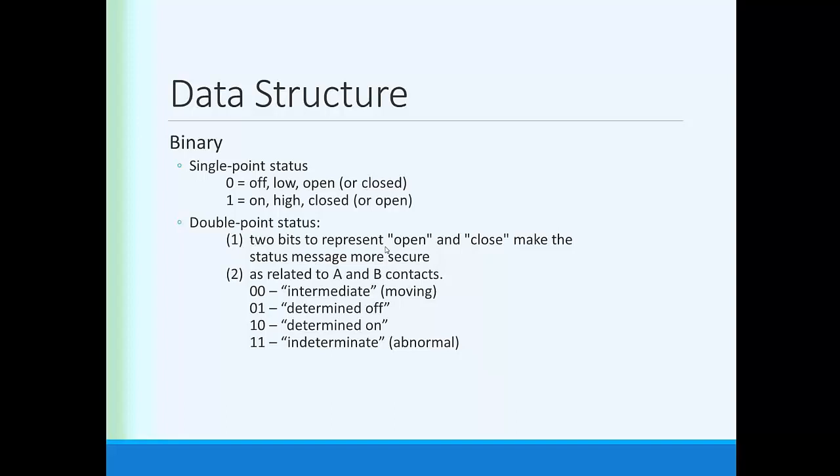A breaker operates almost instantaneously, in a matter of milliseconds, microseconds for that matter. But a motor-operated disconnect is closed, there's current passing from the bus into a breaker. Let's say you take the bus down for maintenance. You open the breaker. Boom, there's no current going through it. Now you have to open the motor-operated disconnect to de-energize the bus for maintenance.